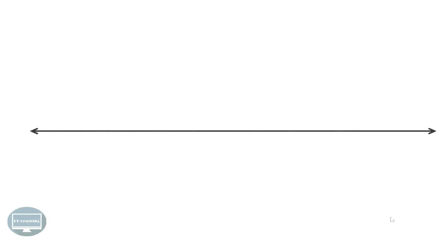Now, as we have already seen, sigma x is equal to 100 MPa and sigma y is equal to 30 MPa. So we can take a suitable scale, that is 1 centimeter equal to 10 MPa, and we can draw two axes. Let us try to understand the significance of these axes. On the x-axis we have the normal stress, and on the y-axis we have the tangential or shear stress.